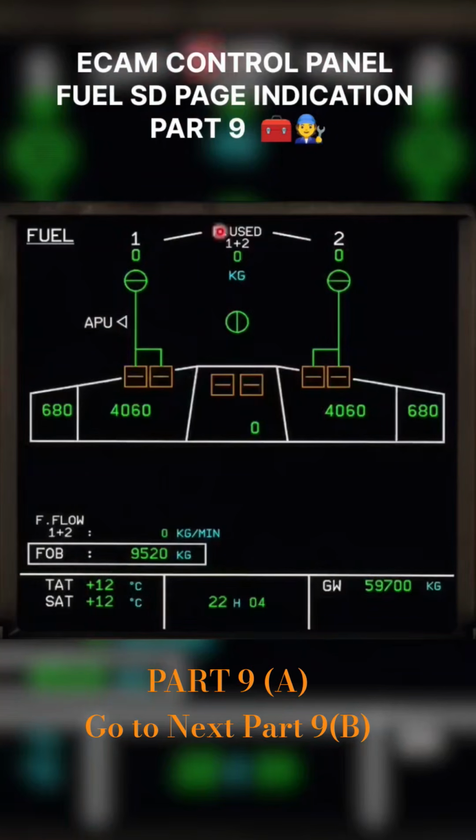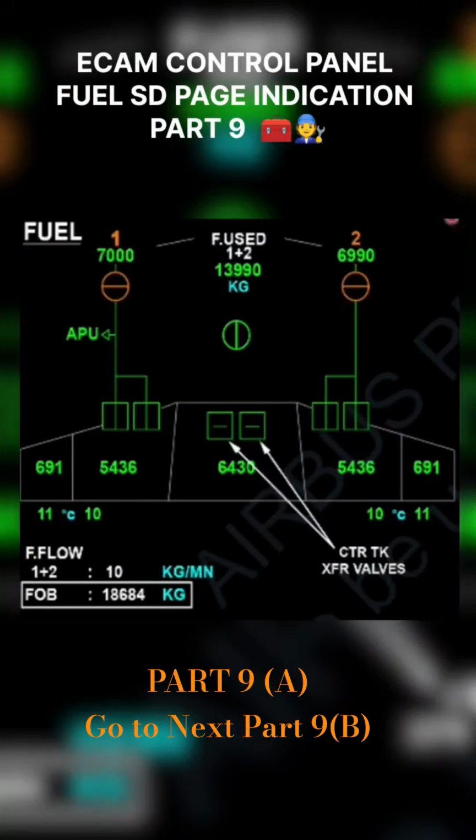If you look at the top, there is a fuel used quantity 1 plus 2. This means number 1 engine and number 2 engine. Suppose number 1 has used 300 kg and number 2 has used around 400 kg, then 300 plus 400 equals 700 kg total fuel used quantity on the fuel SD page. In this example, engine 1 is 7000, engine 2 is 6990 kg, giving you a total of 13990 kg. So this is all about the fuel used quantity by engine 1 and engine 2.